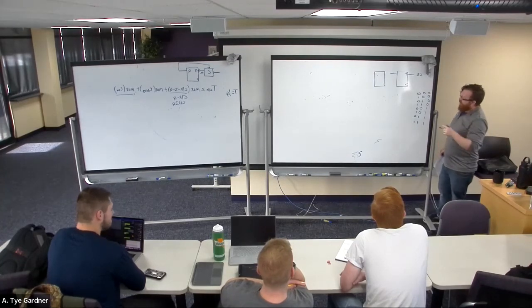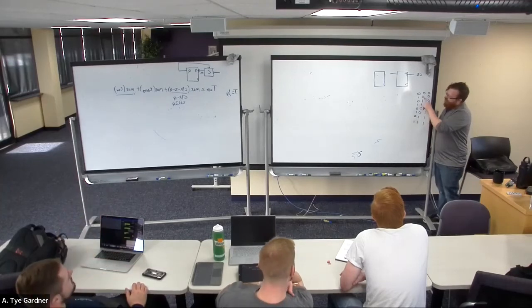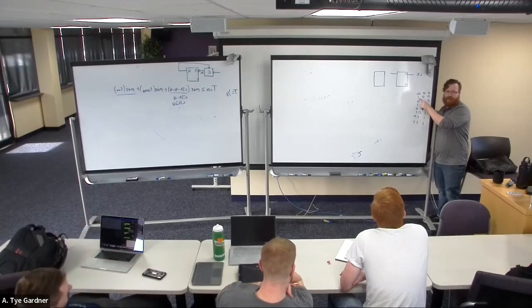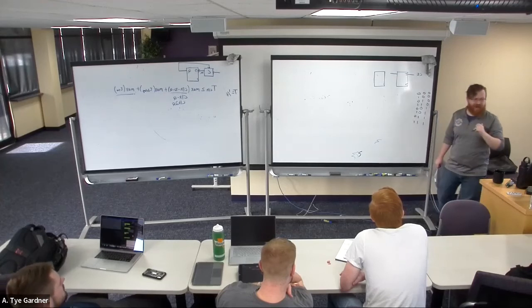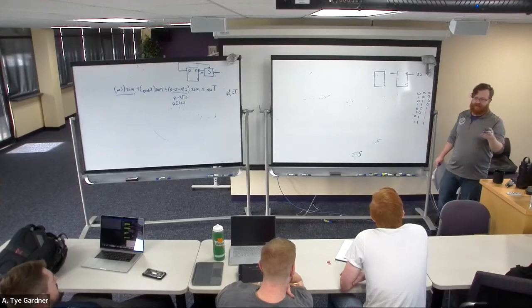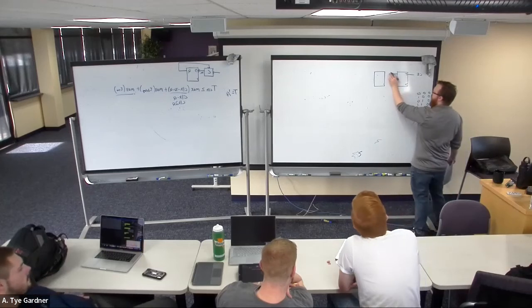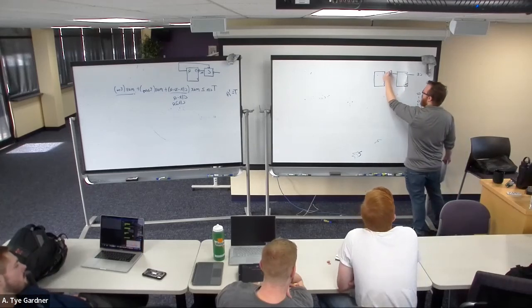But what you'll notice is that the second column, we toggle every time the output of the first one is 1. So this one is toggling at half the rate of this. So if we say, let's go ahead and update when the other one says 1 in my next one, which is another way of saying AND, right?